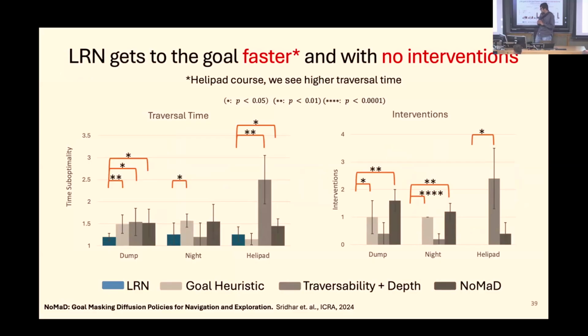Also, a quick note regarding Nomad: systems like Nomad aren't traditionally designed for these waypoint navigation scenarios that we see in off-road environments, but I think doing some of these tests does highlight the fact that in waypoint navigation, and especially unstructured environments, having a goal image as context is usually not enough. So you need more information in terms of geometry, or if you want to use a system like Nomad, maybe you need a more dense topological graph.